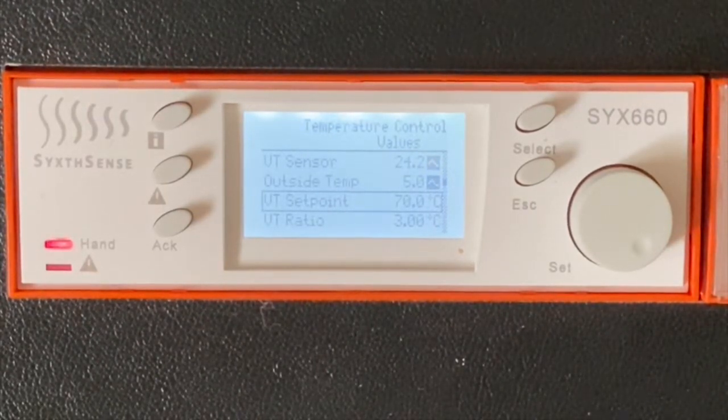So what I would then do is go and inspect the radiators in that circuit, make sure they're getting warm, especially warm where the room sensor is located. It's essential that the room sensor is placed in a heated location in order for the optimization to function correctly. And we want to make sure that those TRVs are turned up to maximum, and that the flow temperature is actually being sent and received at those radiator locations. Okay, that's about it for now.